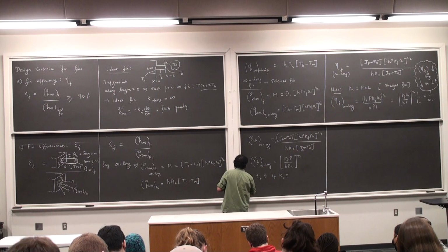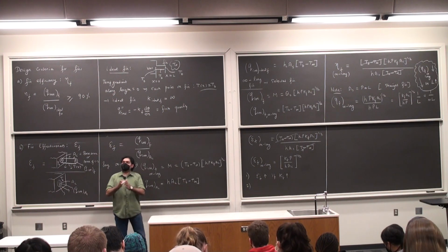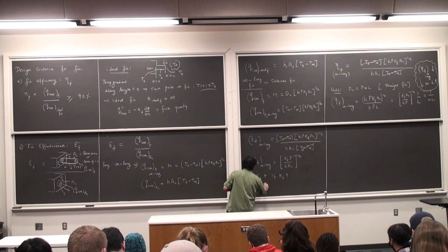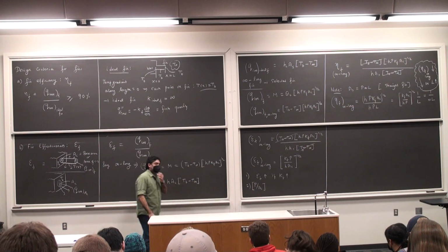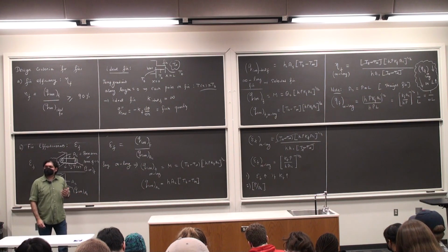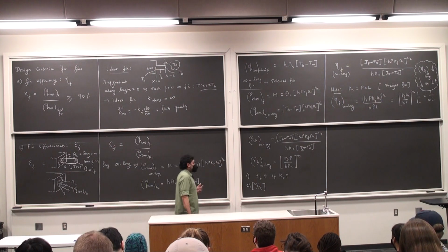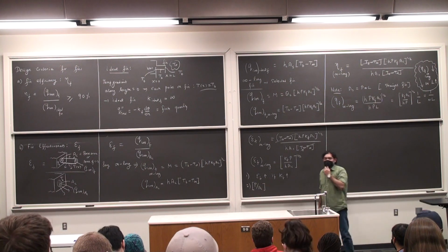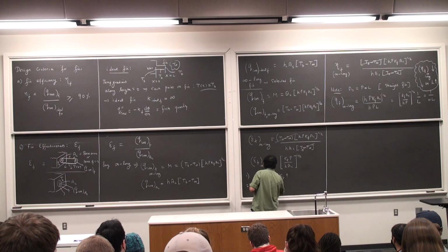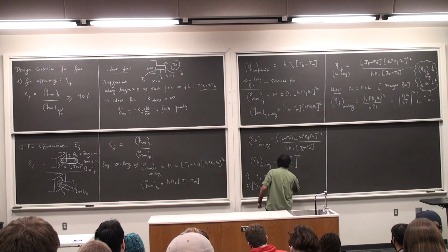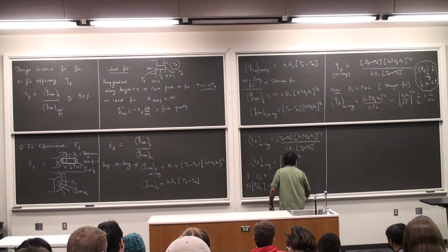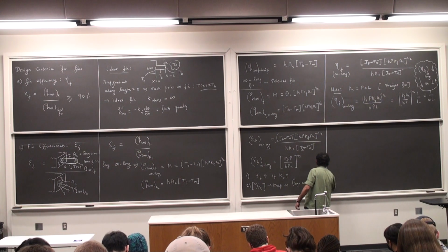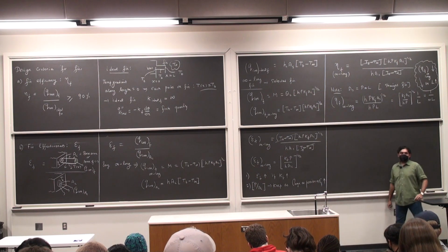Second, this is more of a geometric consideration. If I take the ratio of P by AC, which is the perimeter by the area of cross section, which gives you some kind of a characteristic length feature, I want to keep this ratio as large as possible so that the effectiveness is high. And if I do that, the effectiveness increases.